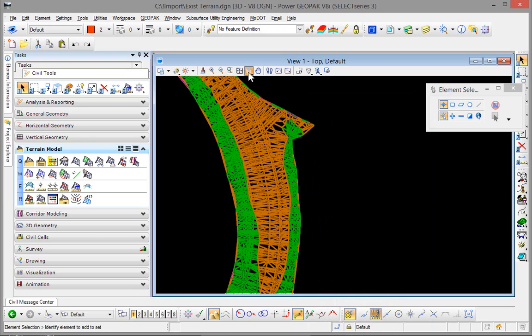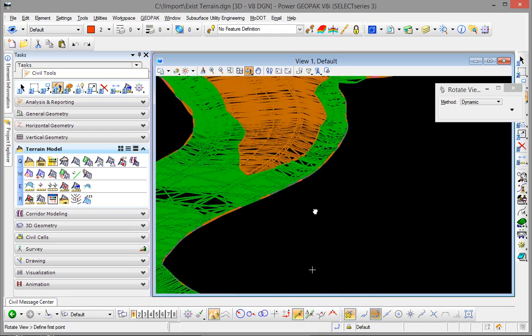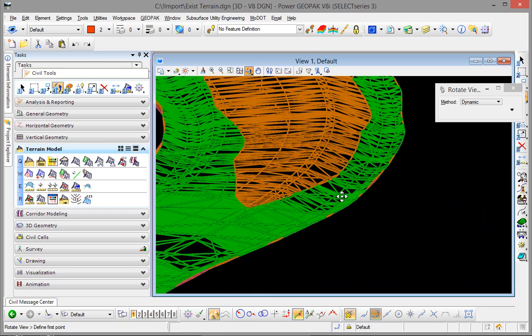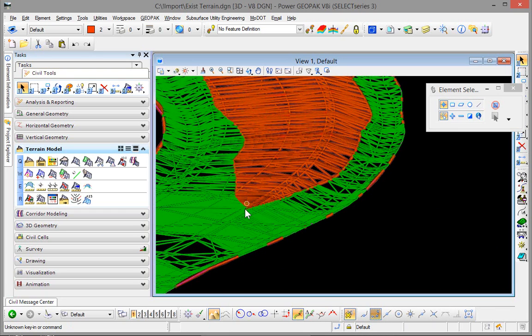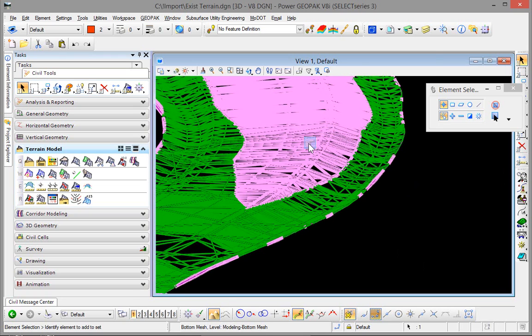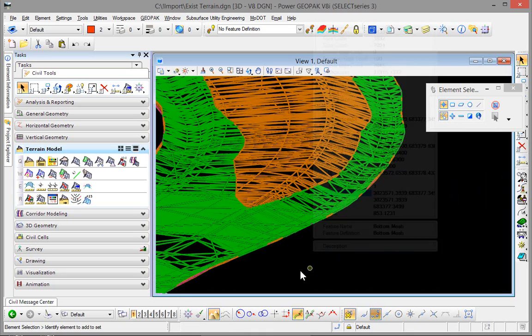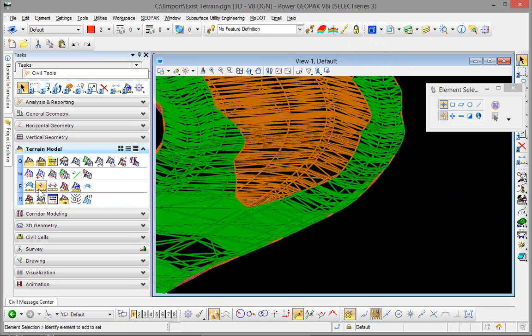And this is three-dimensional, so if I rotate, you're going to actually see a depth to this. It has a top and a bottom. So this is a real volumetric solution, if you will, between the existing and proposed finished grades. It's a quick way for you to check what the volumes are that I'm looking at. And so you can see the analysis here. Those are the 5 or 6 different options we have for analyzing a terrain model or comparing between terrain models.